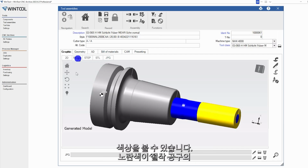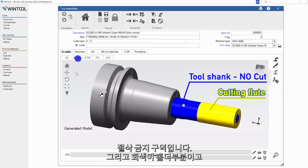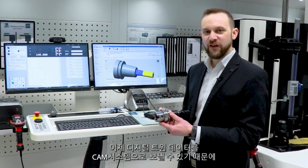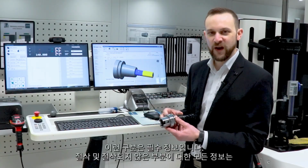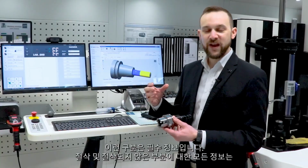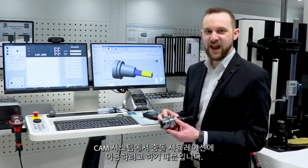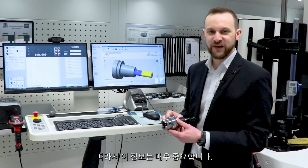And you see here the yellow section, that's the cutting fluids on the cutting tool. Blue area is the shank of the cutting tool, which is the no-cut section. And gray is the holder, which is also the no-cut section of the tool assembly. And this is essential information because we can now send also the digital twin to our CAM system, and we have all the information about cut and no-cut section available, because in the CAM system we want to do the